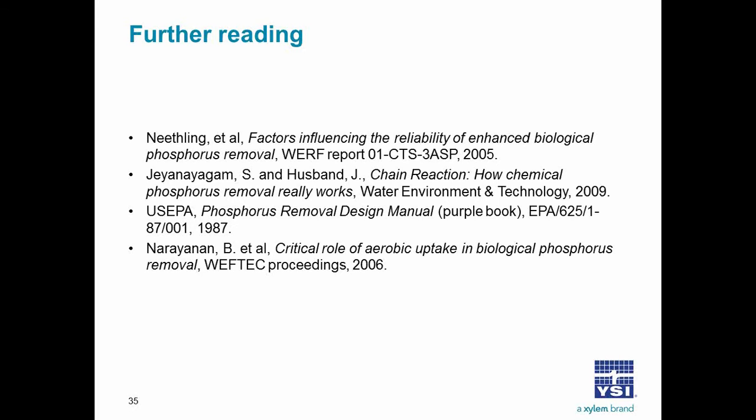And the reason for that is that the removal of ortho-P is really the function of the process. So when you're adding chemical, you're converting ortho-P to total P. When you're doing EBPR, the objective is to put that ortho-P into the biomass. Total P, on the other hand, is a compliance parameter, and so it would be useful on the effluent end of a treatment system.